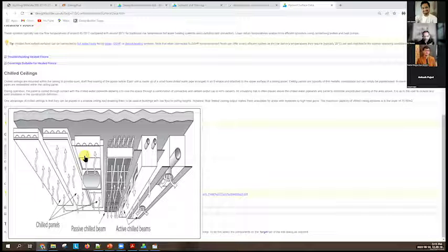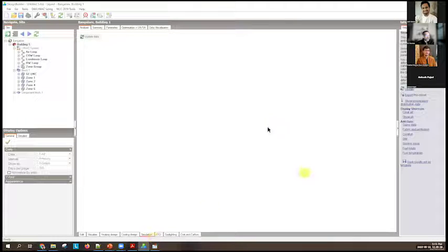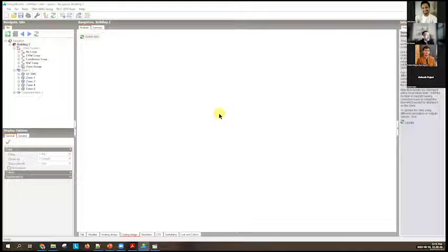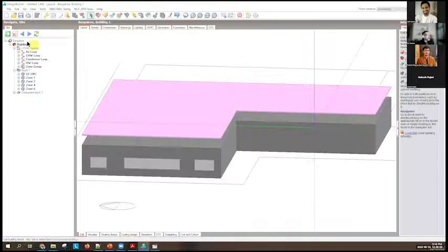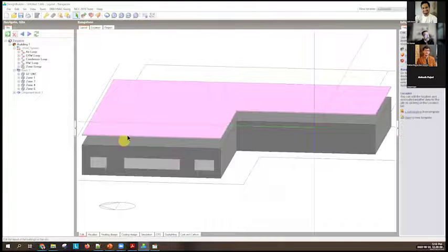DesignBuilder is not a design tool for air conditioning systems. It's an energy modeling tool in which you can put a system. So you can't really do, well, you can, but you have to actively work on it. You can size things. So within DesignBuilder, for example, if you go to the cooling design, and in one of those webinars, this one, I have addressed how to do load calculations. You can set design conditions at the location level.